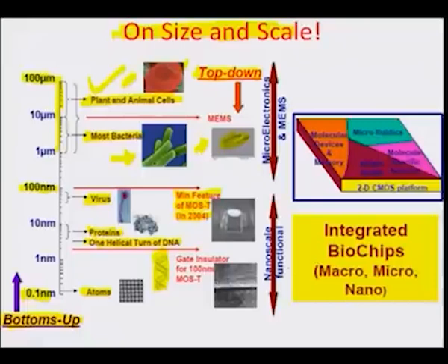And for such a 100 nanometer device, the gate insulator region, which may be this region, is as low as a few nanometers, about 2-3 nanometers or so. So you can see that even at the molecular level, there are these features and structures which are created, which rhyme very well size-wise with these molecules. So it gives you an opportunity to interact with the biological world more appropriately by building micro size